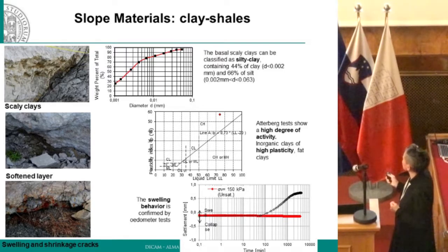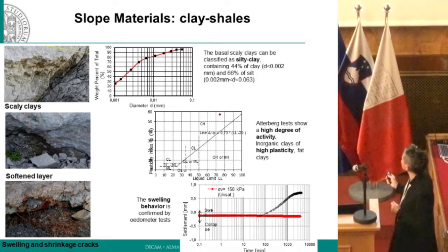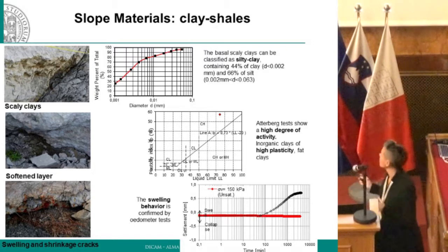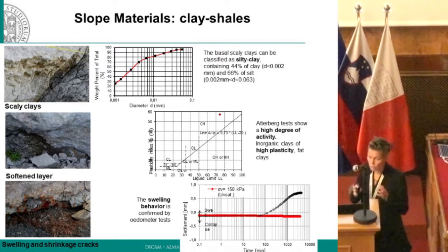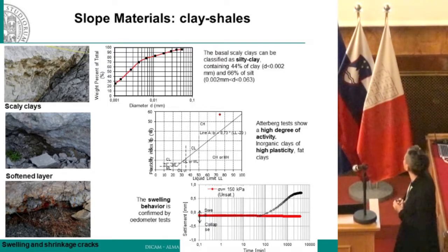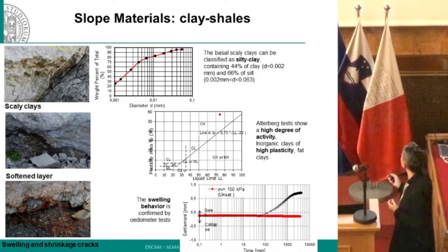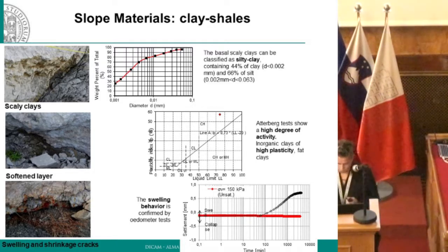Anyhow, we thought that this was a quite important part of the story, because if you start from scaly clays, and if you soften them, you will end up with some specific phenomena like swelling and shrinkage, which can be important in the evolution of the phenomena. So actually, we found that these materials have a very high degree of activity, so they can undergo swelling and shrinkage, and this was confirmed also by oedometer tests.